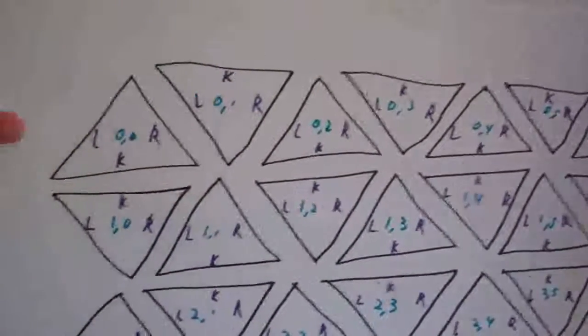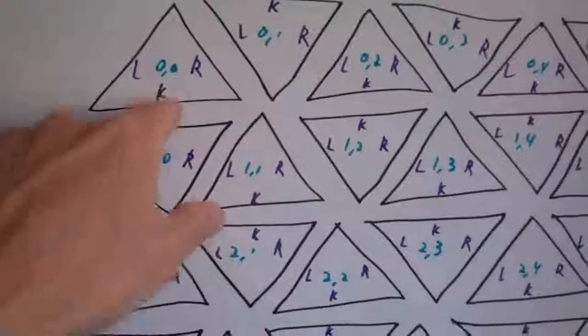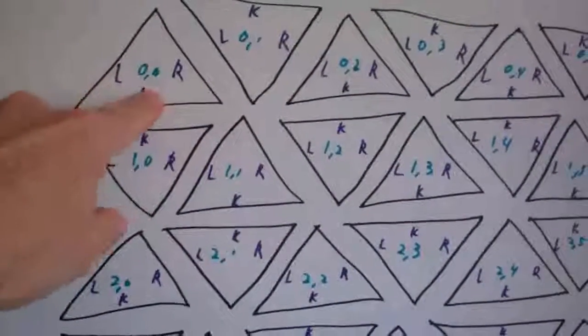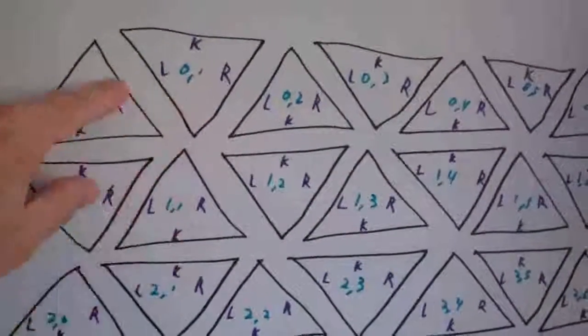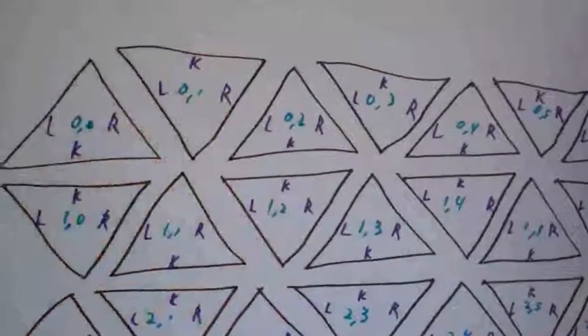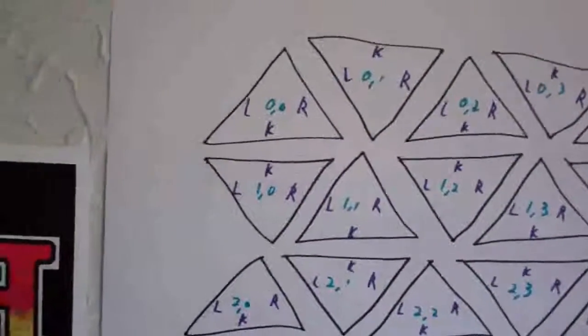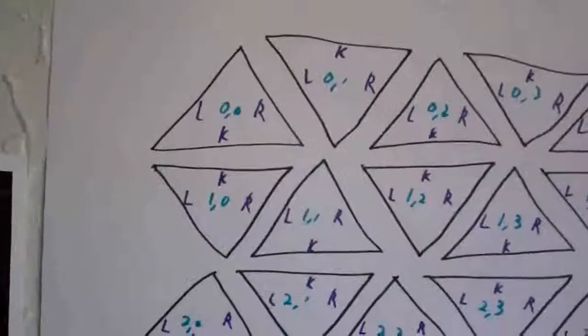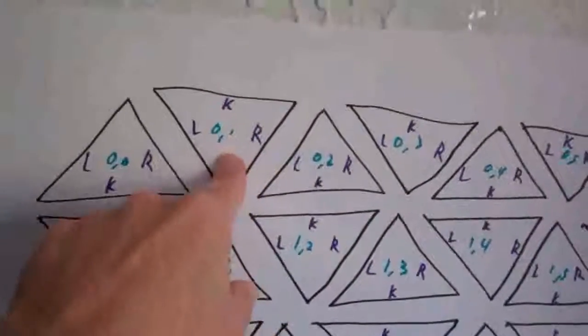We're sending one analog input into the left side here, another analog into the left side here, which is routed up through the K side. Cell 00 multiplies those two inputs from L and K, sends it out the right, and cell 01 takes the value from the left and sends it out the K output. The sim engine is set up right now to read inputs from any sides that we want, but the only output that's sent back for conversion to an analog signal is coming from 01K output.